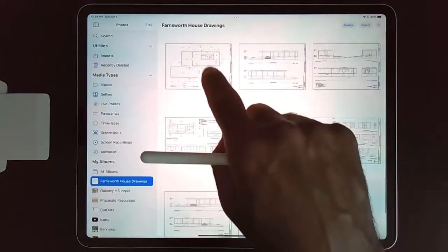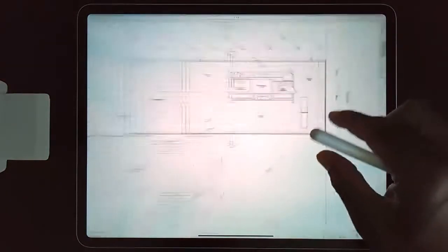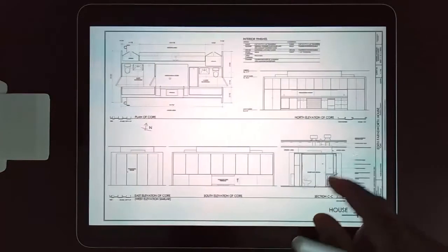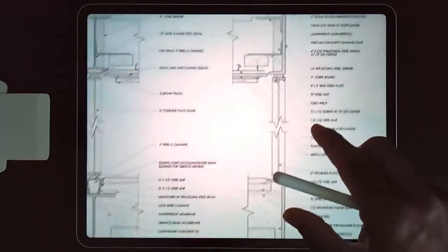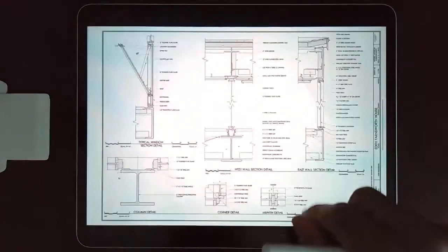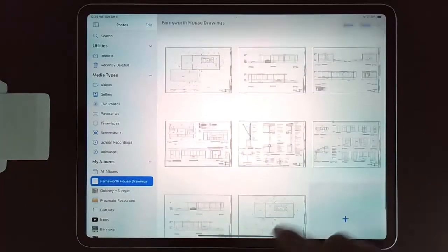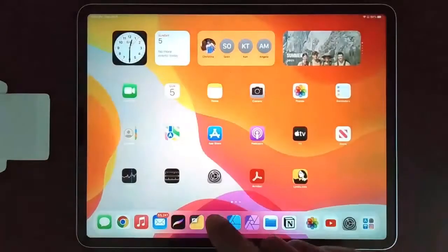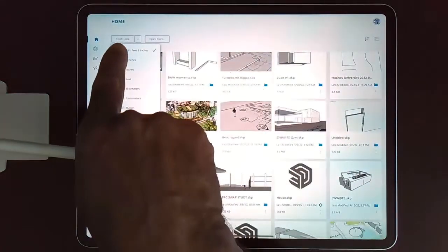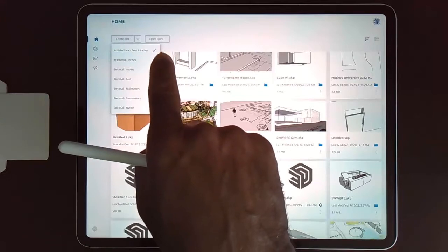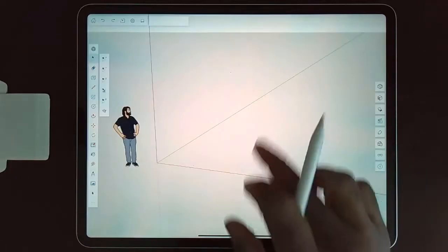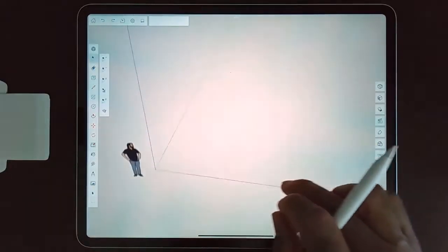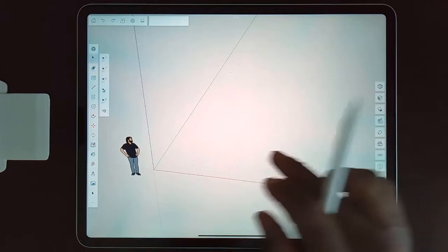So in here, we're going to maybe take a look at the floor plan and see if we also have some elevation drawings, some interior details, and some exterior details that are fairly well drawn so that we can get a sense of how the house was constructed and get some vertical dimensions as we go along. So we're going to start in our file. We're going to go to the architecture feet and inches template and say create new, and we see our blank file that we can start drawing on.